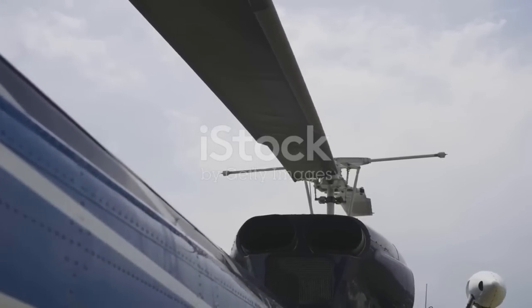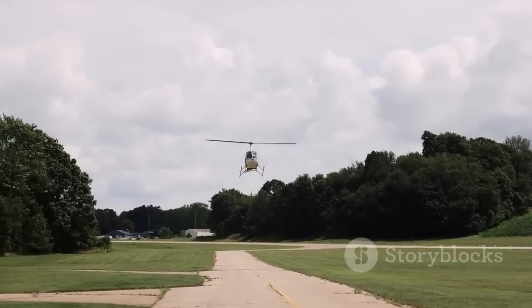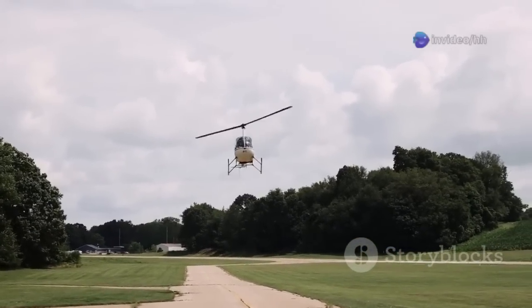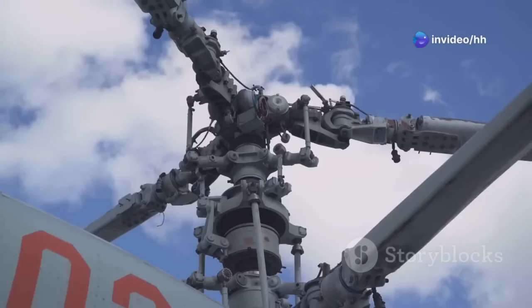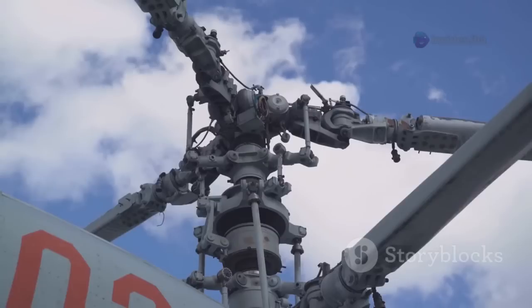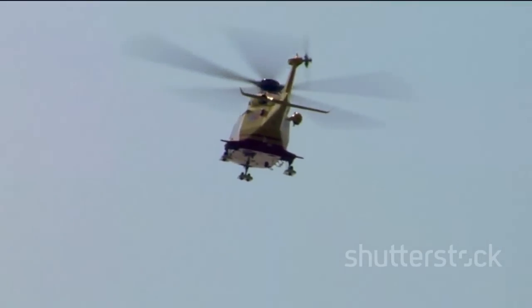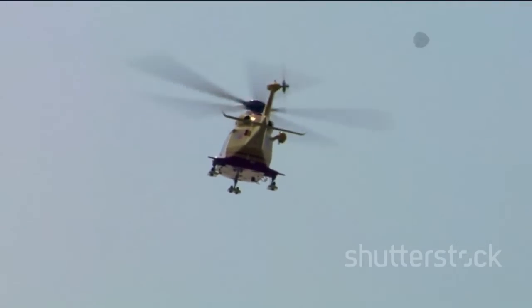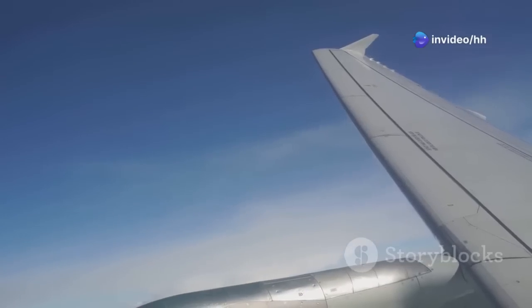Section 6. Blade span and chord size matters for lift. We know that the shape of an airfoil is crucial for lift, but size also plays a significant role. Two key factors are blade span and chord. Blade span. As we learned earlier, this is the distance between the tips of the rotor blades. A larger blade span means a larger surface area for air to flow over, resulting in greater lift. Think of it like having bigger wings on an airplane.